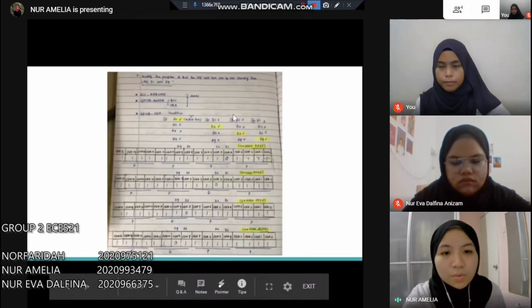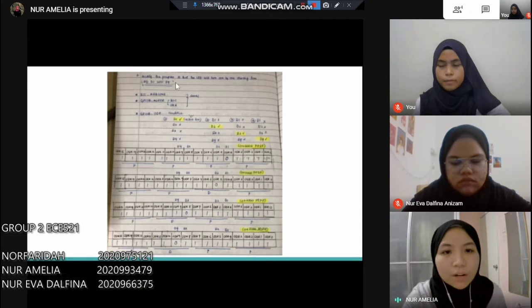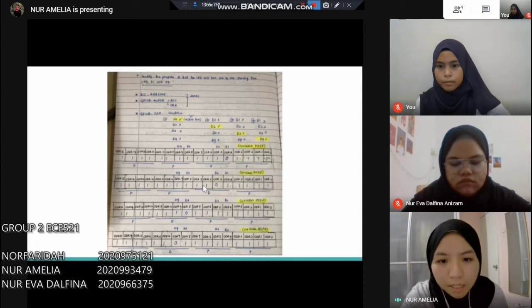So this one is the manual for modifying the program to turn on the LEDs one by one. As we can see here, there are 4 conditions. The first one is to turn on D1, so the value would be 0x0000FFEF. The next condition, we need to turn on D2. After keying in the active logic low, the value would be 0x0000FFDF.